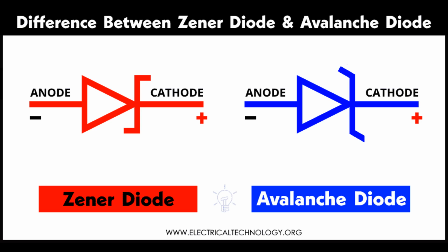5. Current voltage, IV, characteristics. Forward characteristics. Similar to a regular diode, the Zener diode allows current flow when the forward voltage exceeds the threshold. Reverse characteristics. When reverse biased, the current remains minimal until the Zener voltage is reached. At the Zener voltage, the diode conducts heavily, maintaining a stable voltage across its terminals.